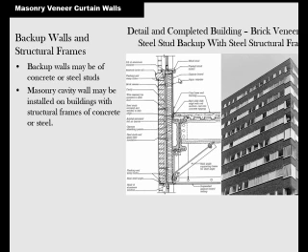And then you're going to have, let's see, here's the angles coming down. It's attached to this steel strut. Then this ledge angle is right there. And then your brick piles up to the next floor. If you looked closer, you would see the flashing and all of that stuff. This is just regular batt insulation, it looks like, behind the sheetrock. And then another layer of sheathing to provide strength for that, and then there's an air gap.